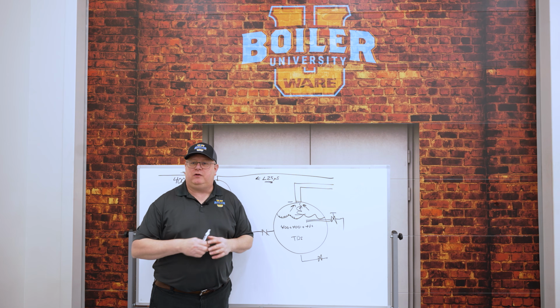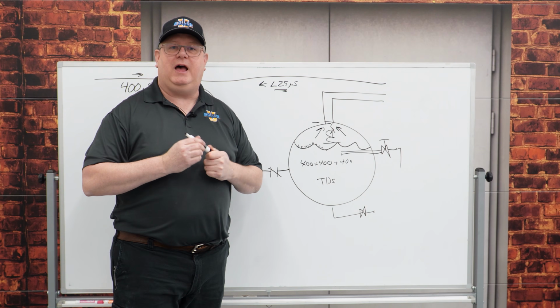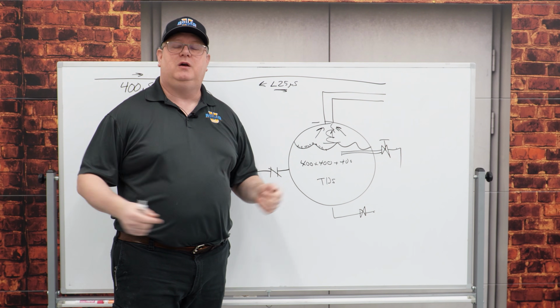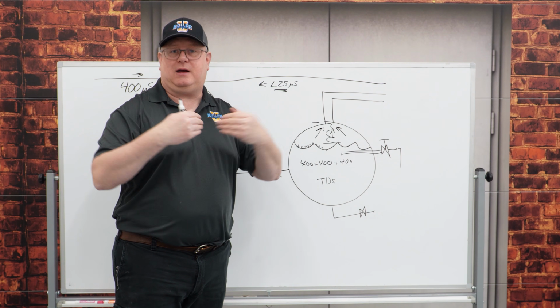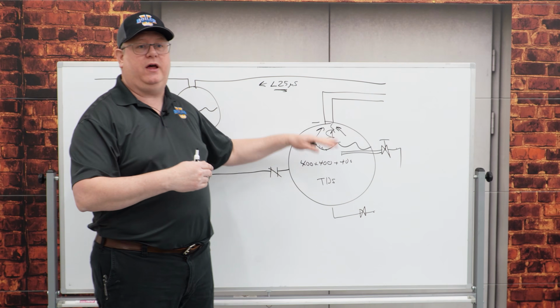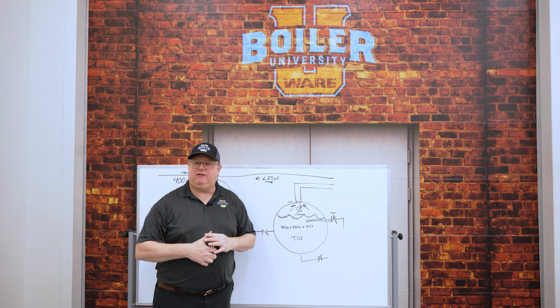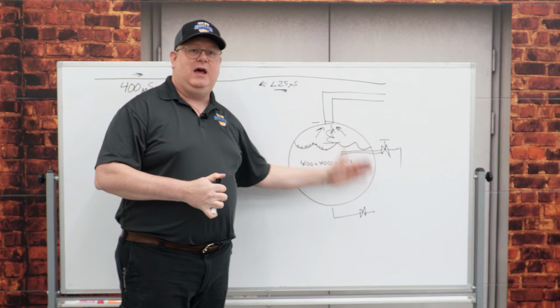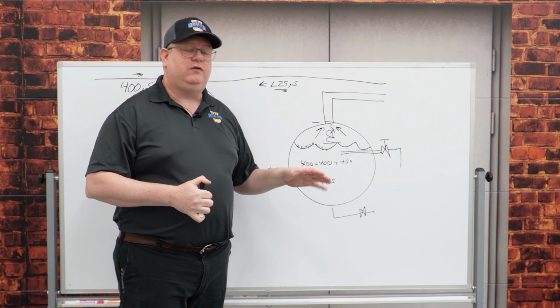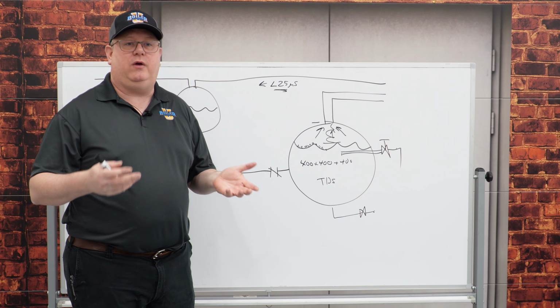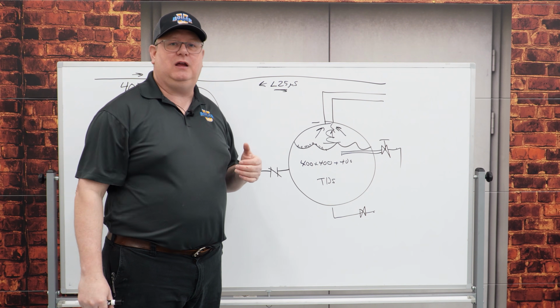So just this week we had a technician starting up a boiler, and they boiled it out and the boiler was clean, but putting steam into the system, which had been down for a little while, brought back a lot of garbage from the system. So they were getting low water trips all over the place. We had to measure the conductivity, and it was high from those solids coming back. He did some aggressive blowdown, and that remedied the situation. So if you don't have a surface skimmer, you may have to do more aggressive bottom blowdowns at intervals to keep that conductivity in line.